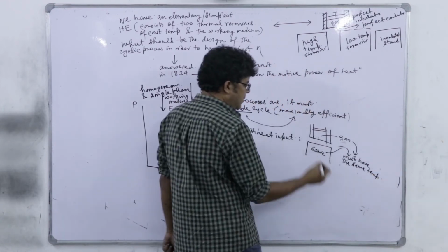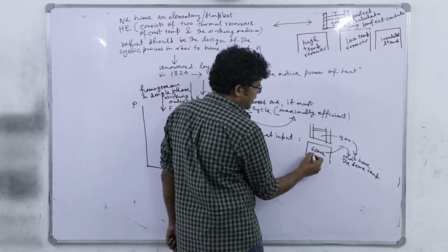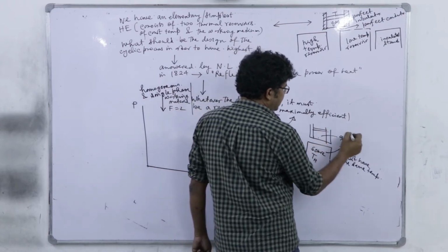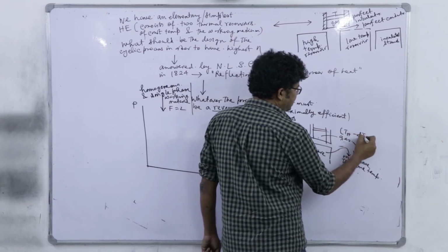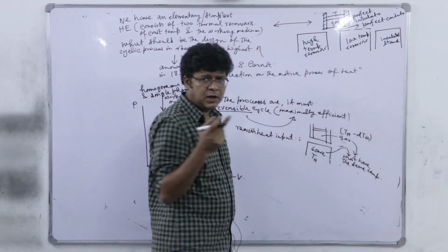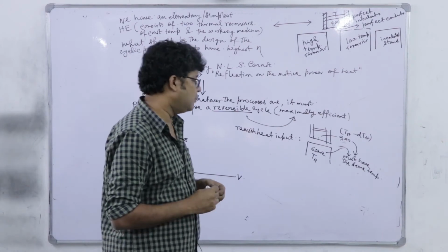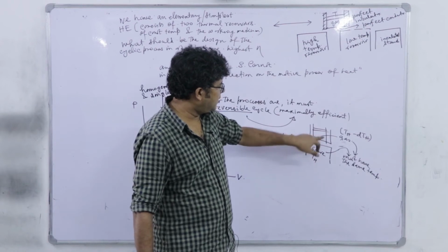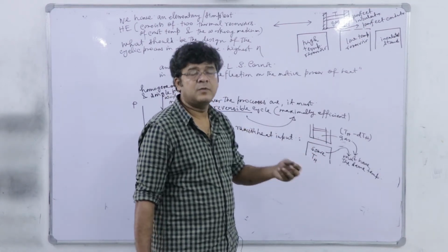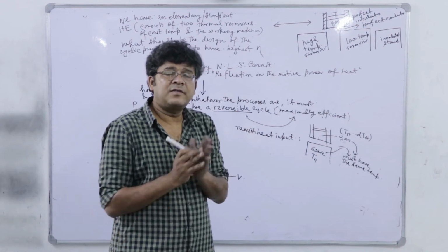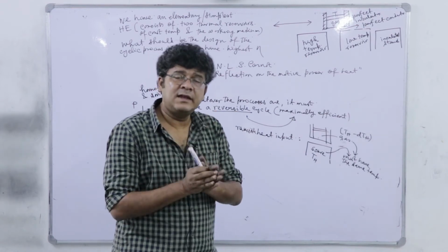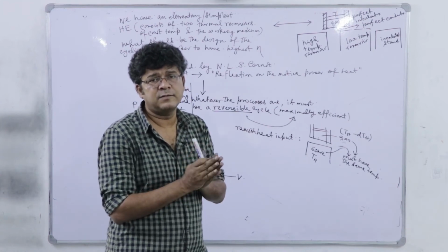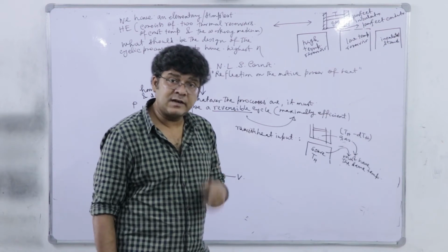Exactly the same it will not be: if here it is TH, here it should be TH minus dTH, differentially small, which we can consider to be the same. So, the source temperature and the gas temperature must be the same, which means the driving force is 0, and then we can implement the condition of reversible heat transfer with a constant temperature source.